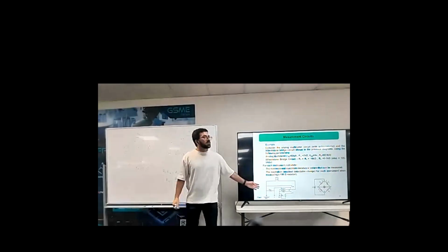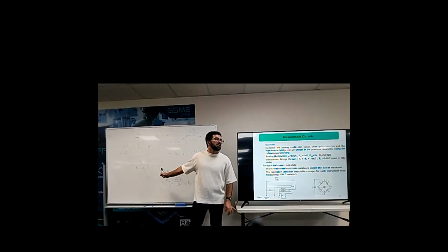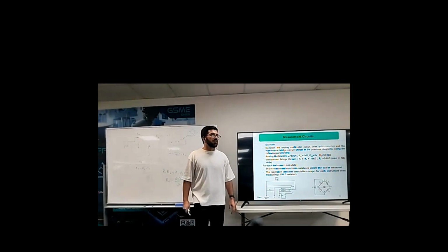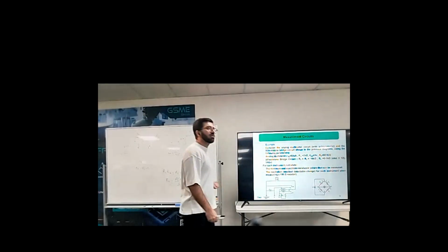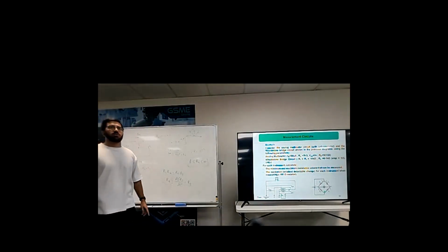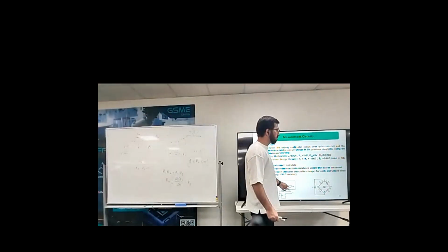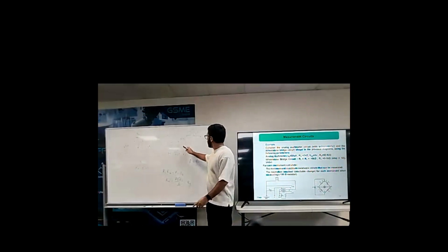And how much is the smallest resistor that we can measure, that means the sensitivity, with these two measurement tools? When we are measuring 100 ohm, how much is the sensitivity of the multimeter we calculated? Can we measure 100 ohm with this resistor? We cannot because of the internal resistors. The minimum is 8K.